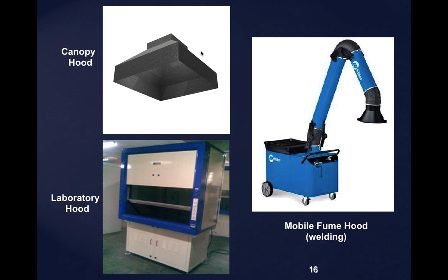The problem with that is that it introduces a lot of turbulence, and it reintroduces a big pressure loss, a big energy loss. We don't want that. We want a system that's designed so it's balanced and we don't need blast gates, so that as soon as you turn the switch on, the sizing and lengths of the ductwork balance the entire system. So you don't need to control the amount of air going from one hood or another hood or through the whole system.